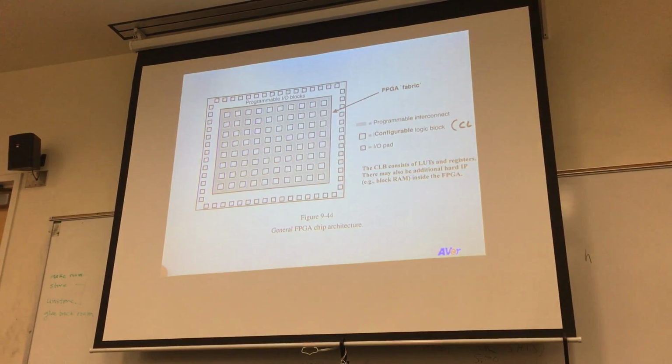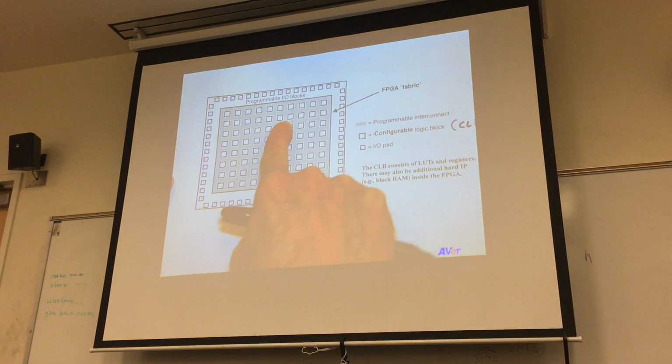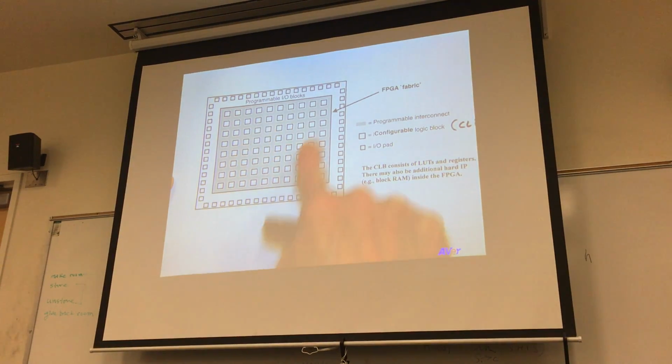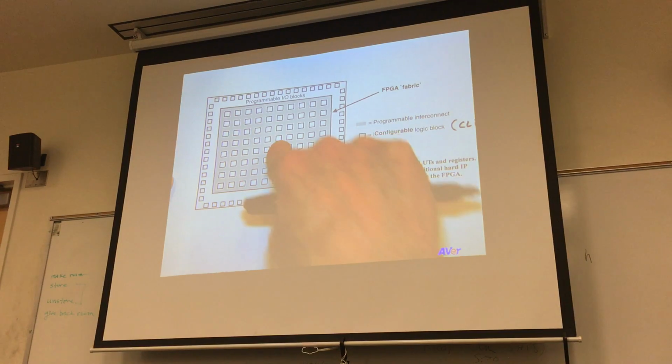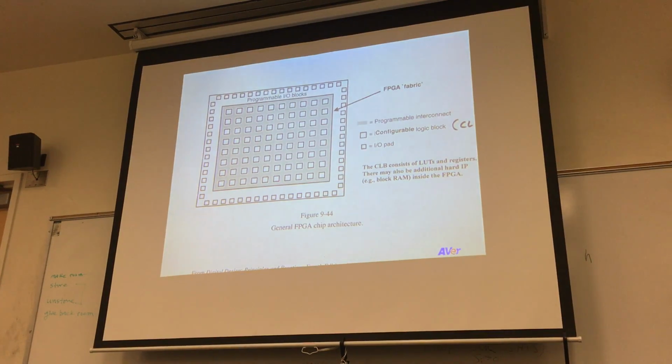The third thing that you have to program is the interconnection. You've got to hook everything together. The input-output pads have to bring signals into the configurable logic block where the data is going to be processed in some way, and the outputs of some of these configurable logic blocks will go through output pins, so you have to interconnect the outputs of these configurable logic blocks to some of the I/O pins. So the three things you program.